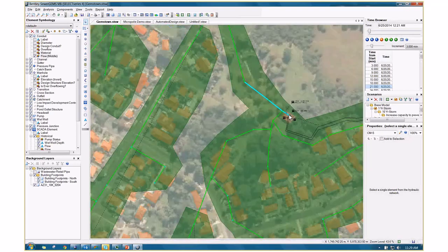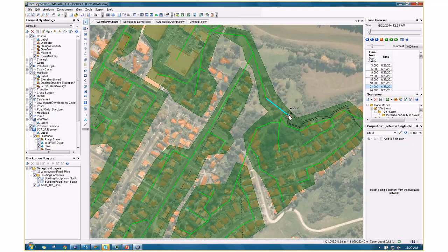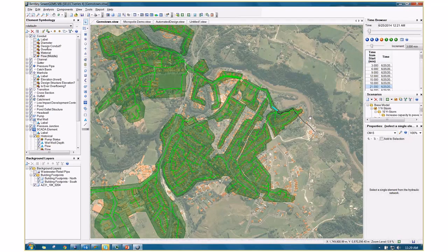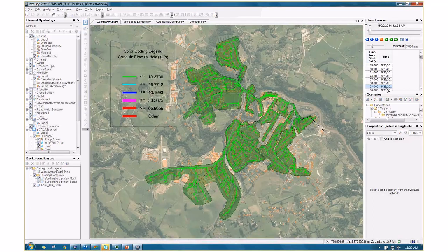Right, and now this was just to explain how it calculates things, but let me now play it completely. As you can see, time is changing, and after every 2 to 3 minutes it will calculate results for you dynamically, and it will make you understand how your network will behave in a short span of 5 minutes of rainfall, so that you can check whether your network is safe for a return period of 10 years for a 5 minute rainfall duration, right?